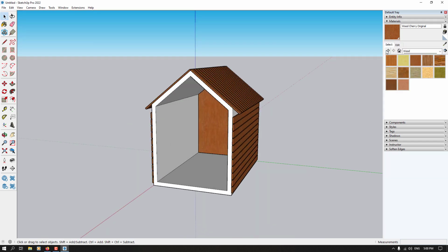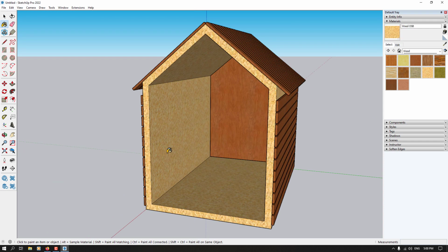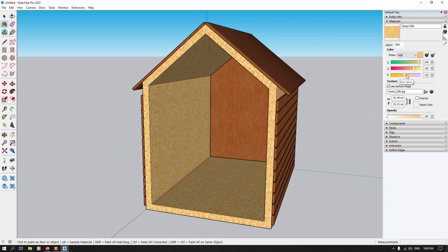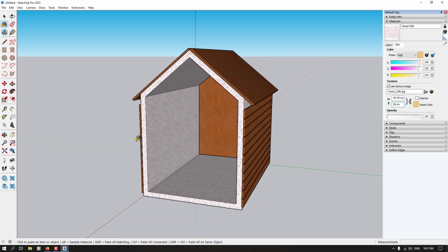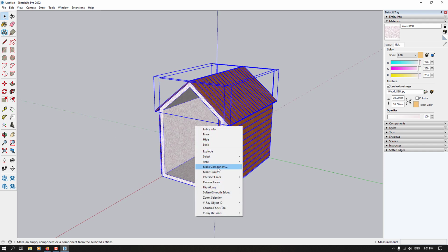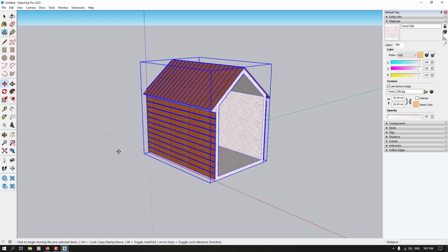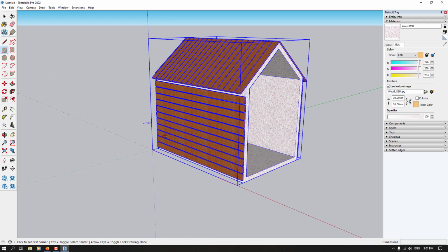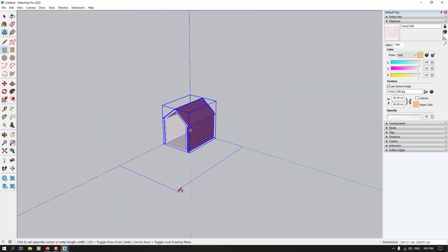So as you can see, only we need some color for our body. I'm going to use wood OSB in here with some type of white color, something like this, and you can adjust it from here. You can change the texture sizes 30 to the 26, and now I think everything is good. So I'm going to select all of them and make some type of group for it. Now I want to check it in the display, and now I want to draw some type of ground for it, some ground about 400 to 400.